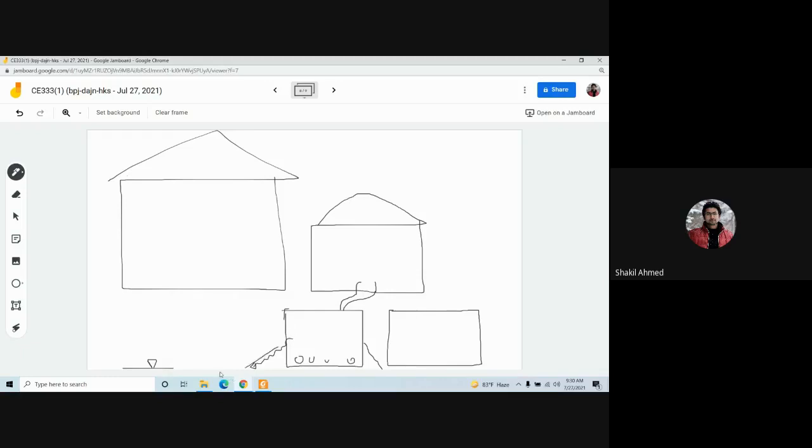So you have to maintain a distance of maybe 10 to 15 meters at least. It will vary depending on the type of soil. Let's say 15 meters from the location of the pit, so that the pollution does not reach the groundwater. Clear?